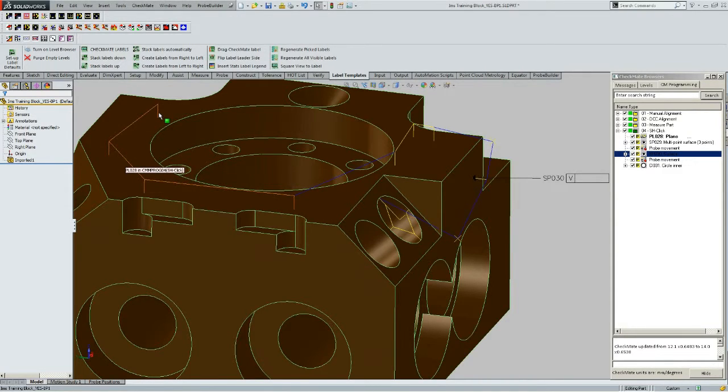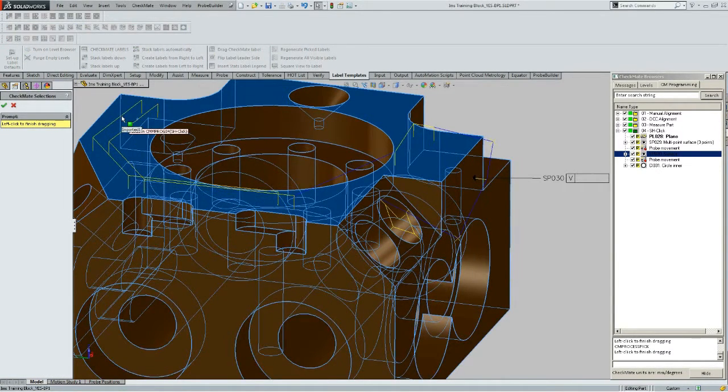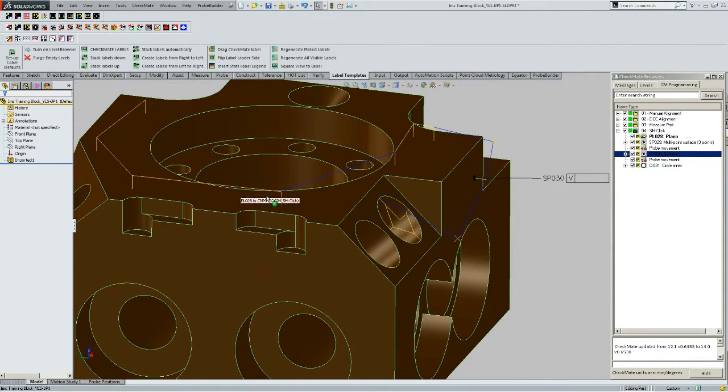Now that was selecting on the individual hit. Now if I try holding the Shift key down and grab the yellow tie line at the top, I can move the entire feature around. And again, this is just holding the Shift key down. Click again to drop it off. So we can move the individuals around, or we can move the entire measurement.